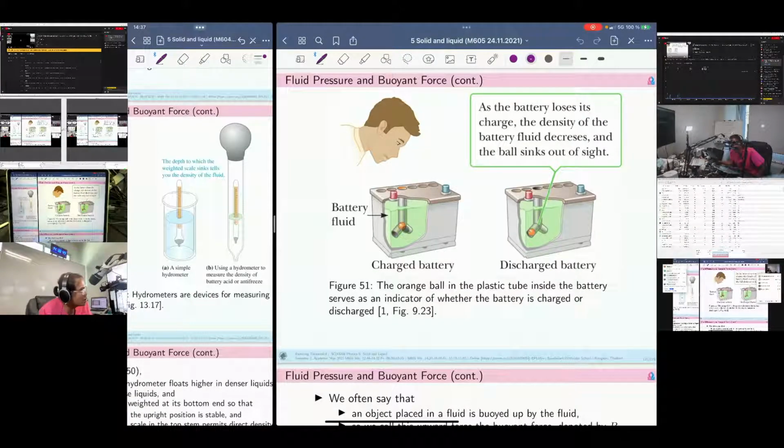If the water is not pure, there will be internal resistance, and it will obstruct the current flow out of the battery. That is not good, because you have reduced power, a deteriorating ability of the battery. It's better to use pure water. This liquid is a mix of pure water and the acid.